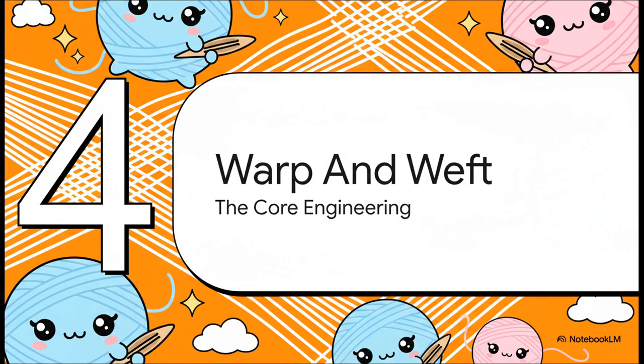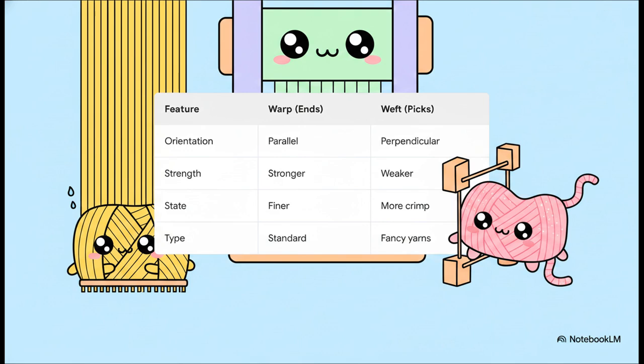All right, Section 4, Understanding warp and weft. This is where we get into the real engineering. The vertical yarns are called warp yarns, and individually they're referred to as ends. They run perfectly parallel to the finished edge of the fabric, which we call the selvage. Warp yarns absolutely must be highly twisted, finer, and much stronger, simply because they endure extreme tension on the loom. The horizontal yarns? Those are weft yarns, individually known as picks. They run perpendicular to the selvage.